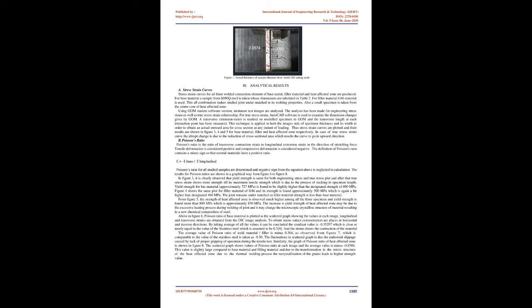Once the images are imported into the software, surface components are created for DIC analysis within the surface throughout the complete image dataset. Facet size and point distance must be chosen when a surface component is created. The first step is determining how many pixels the software uses to find the points. If the value is small, it will trace closer strain values. Facet size should be kept as low as possible but large enough to track all the points over the whole sample test.